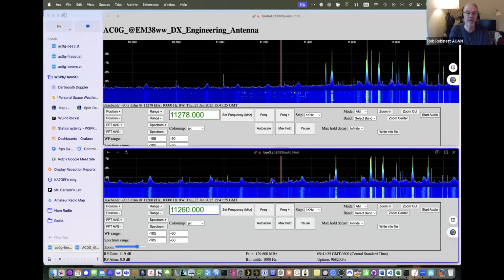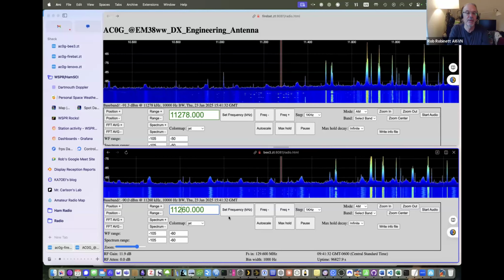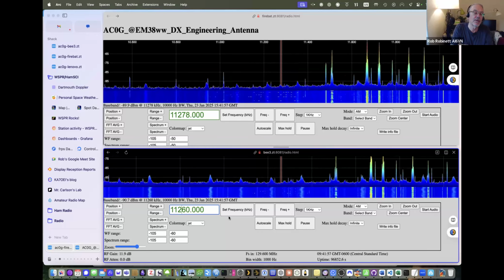I think that if you had a blocking transformer, Michael, do you have a T11 in the DX Engineering feed line? No. Yeah, you might. That might help. You might try that out and see if the T11 eliminates that. It may not. It may make it worse for all I know, but it is one way to ensure that what you're seeing on the DX Engineering feed truly is differential. And you might put a T11 at each end of the coax.